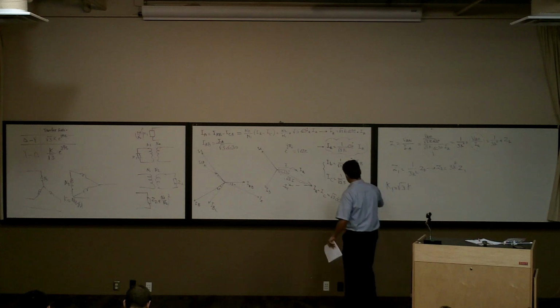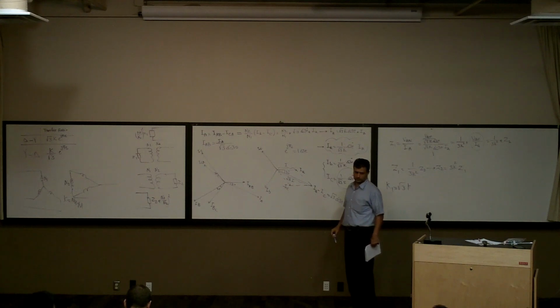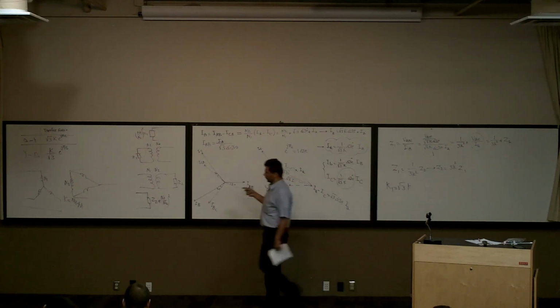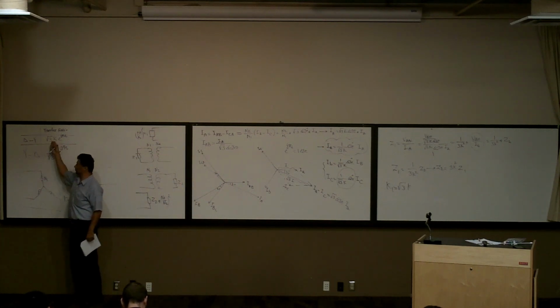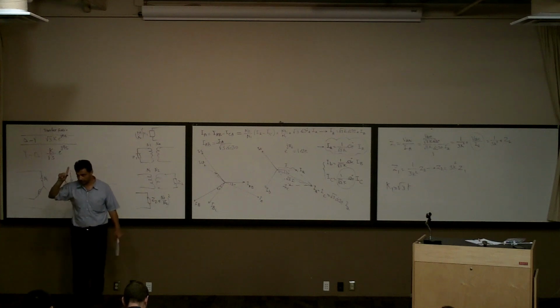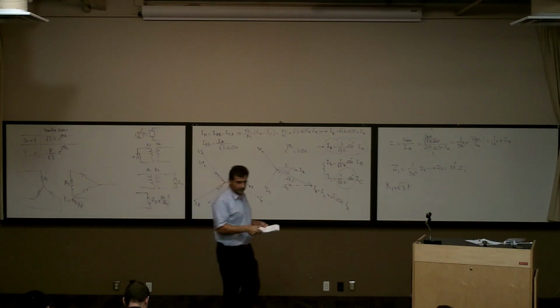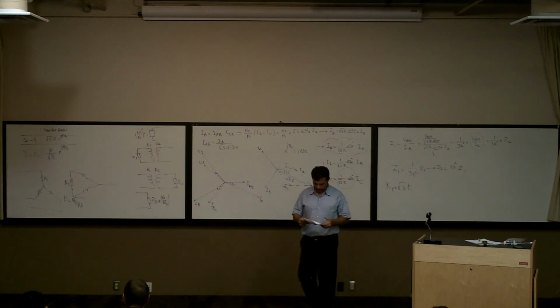So if you remember here, if you are going to get the transfer ratio for the current, what should you do? This is for the voltage, right? You say V2 is equal to this one times V1, or V2 is equal to this one times V1, right? If you want the current, how about that? It's going to be 1 over this, but don't change the angle. 1 over this, don't change the angle. Just keep in mind, you're not changing the angle. Be careful, okay? So look at it here. See, we have the same thing here. We didn't change the angle, right?